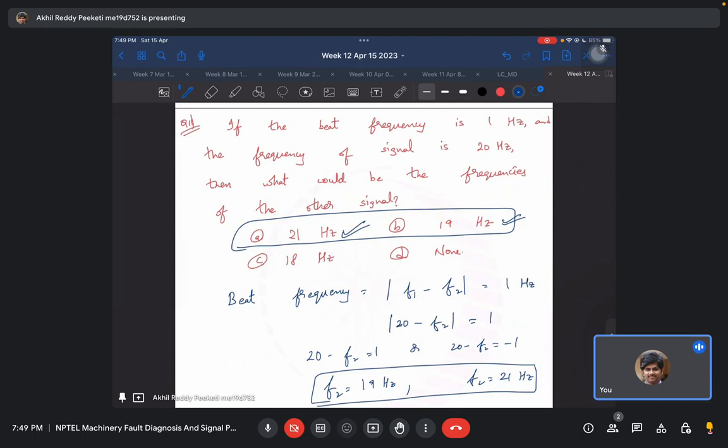If you don't know the frequency of an incoming signal, and if you have a signal generator, you can use this phenomenon to generate multiple frequencies and see if the frequency is matching. If there is any production of beat, if beat is forming, then the frequency of the incoming signal is also in the range where you are generating the frequency.